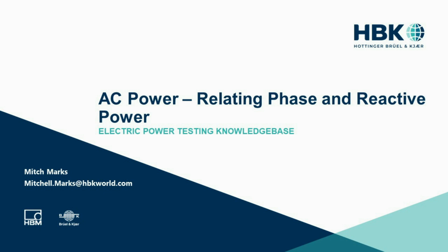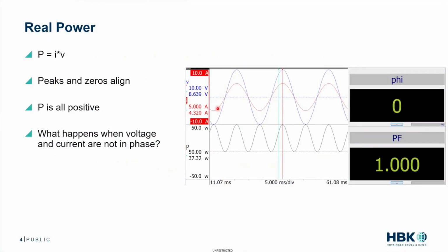So, reactive power and RMS fundamentals. We're going to start really basic. I promise it'll pick up, but for people here who might not understand power at the conceptual level as well, we're going to start simple. Power equals instantaneous voltage times instantaneous current, and we're going to be speaking today specifically about AC power. So everything's going to be sinusoidal or pseudo-sinusoidal.